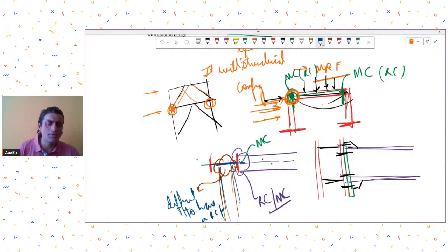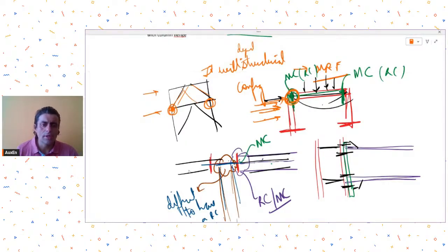Then there are other options. Then there are other jugaad works that you may have to take plate from here, and then come up with some sort of rigid connection, but it's too complicated. So generally, if you are using I-shaped columns, only about one direction you can create moment connections. About the other direction, it is slightly complicated. So depending on all these aspects, you have to think.